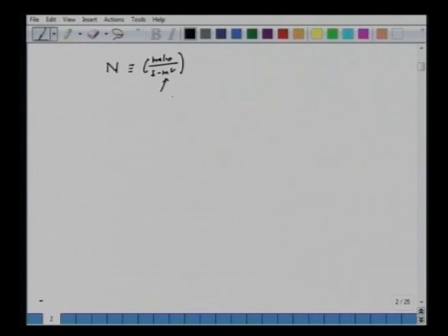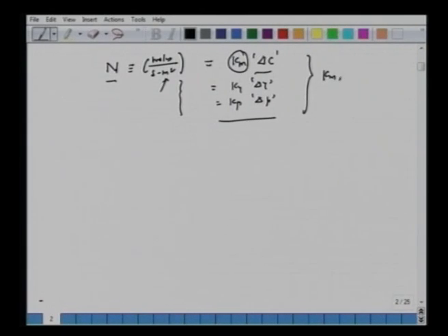So this meter square is the interface area, and we said that by invoking this parameter, mass transfer coefficient, we can have driving force for mass transfer from one phase to another, and we can write in several ways: Km del y, Kp del p, etc. Alright, so this is about the rate one has to measure in terms of mass transfer coefficients, and all these mass transfer coefficients Km, Ky or Kp were shown to be a function of Reynolds number, Schmidt number, etc.